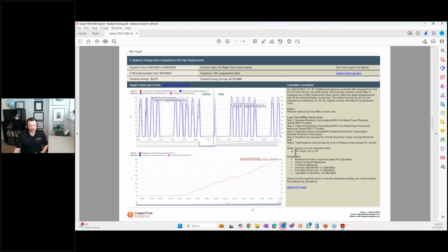But because of the low touch required in order to implement these, versus what is typical, if you're talking about ASO, the ACX piece would be a pretty simple calculation around what maintenance measures am I going to replace with automated commissioning and testing. So if I'm going to stop inspecting my VAVs every 6 months and only repair ones that are showing as broken, what portion of that dedicated budget can I remove from inspection and put somewhere else or get rid of? That would be a pretty easy calculation. When it comes to ASO and we're talking about energy, we include that expected savings in the ASO plan. So as we run the baseline of how it's operating today, and then we propose the measures, we can accompany those with the projected savings associated with them.